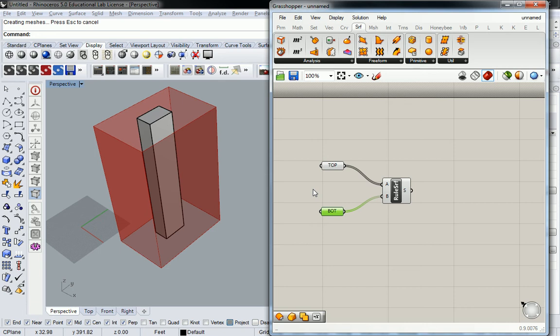So we're going to do it using move, and the only thing we have to change is how many numbers we plug in to move, because if we move it 0 and we move it 1 and we move it 2 in the same command, we've made 3 copies of that geometry. Does that make sense?